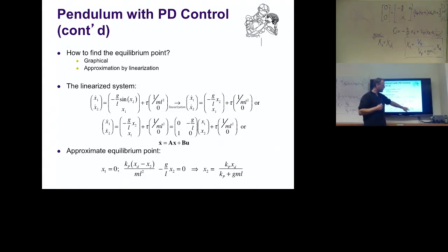And you can just play the game now. So what does it take to achieve x desired, at least an approximation? It's very simple. Let's make KP really big. Let's look at my big equations. KP becomes really big, like 10 million. Then you have 10 million here, 10 million there, and then add a tiny little bit, GML, to 10 million. That means 10 million divided by approximately 10 million is 1. That's actually a very important insight. If we make our proportional gains very big, we can overcome any form of error.